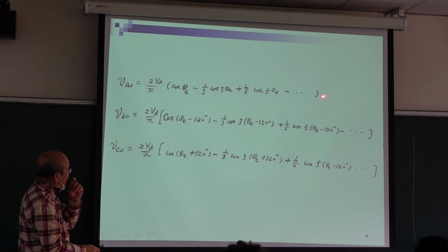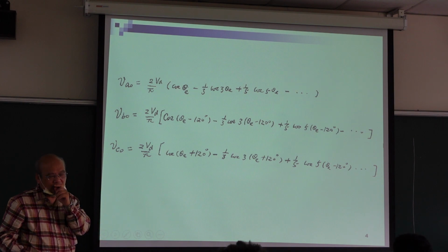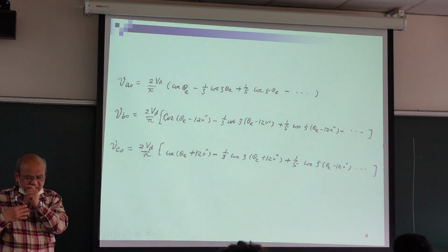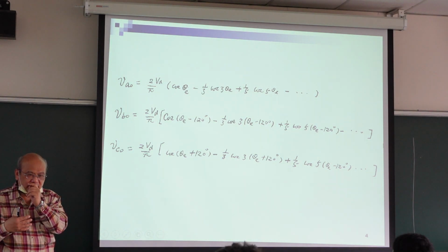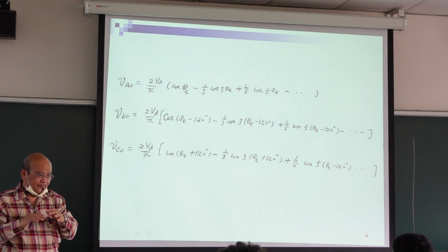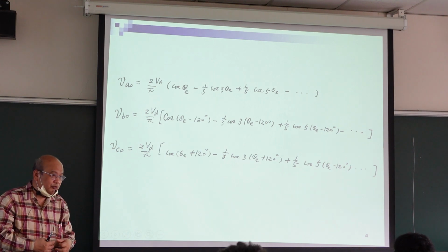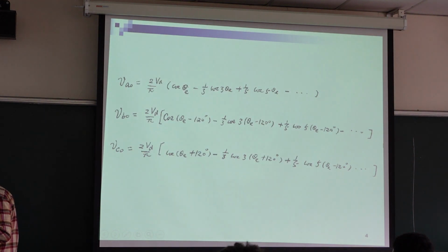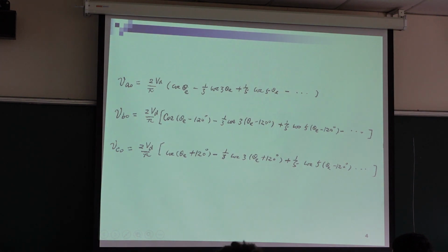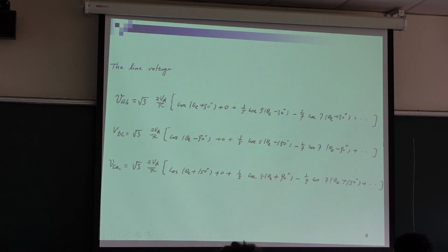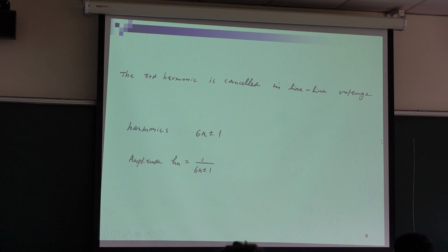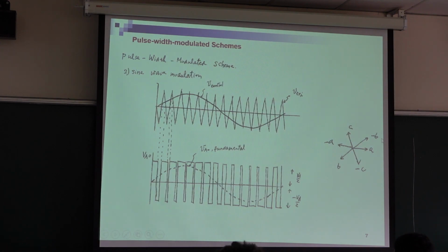114%. So 7th of the fundamental. If we use the six-step voltage, the disadvantage is the harmonics are too huge, right? So how can we solve this problem? You can see this one. The only way is to increase frequency, right? So how can we increase frequency?